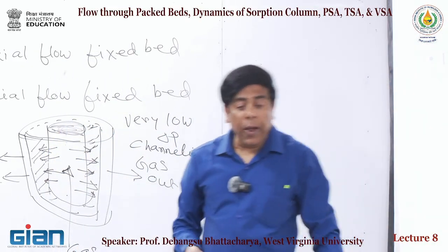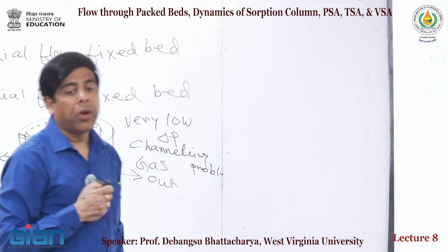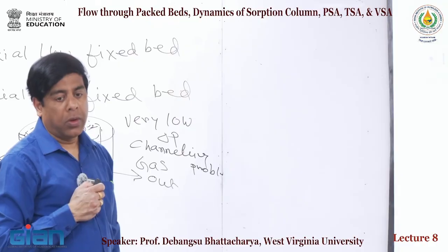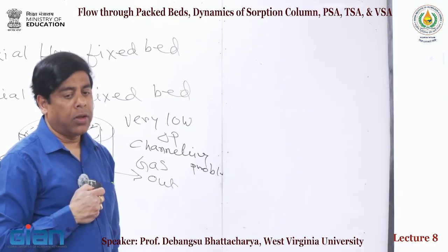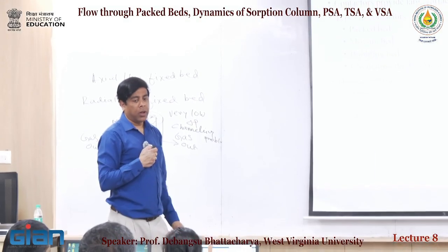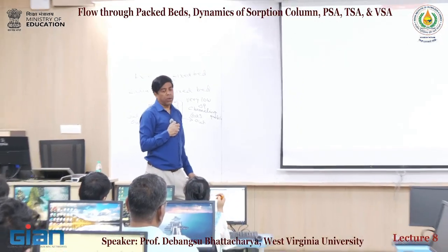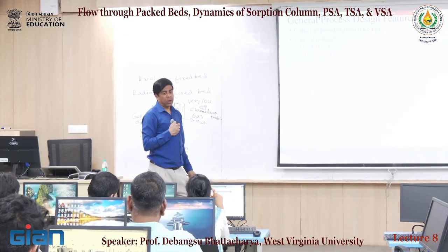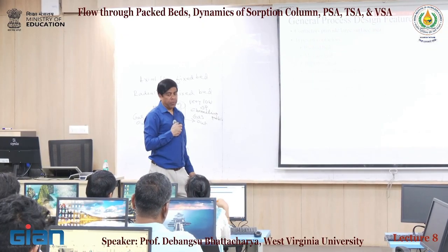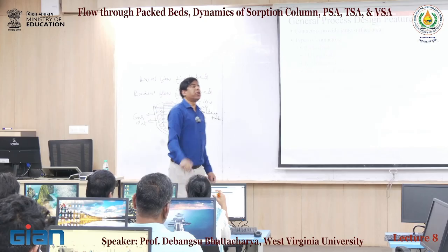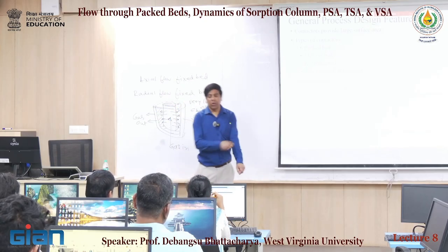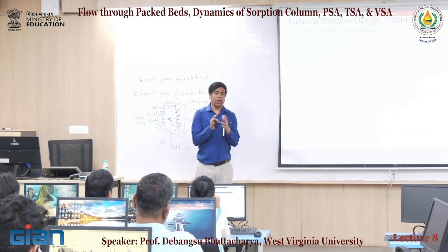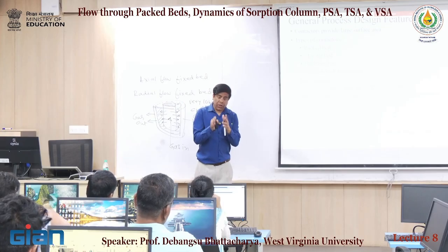You had a question? We have cryogenic air separation units wherein we are separating CO2 and moisture using these dryers. There we have two dryers. One will be in line, the other will be in regeneration. Absolutely. So my doubt is we have packed beds only. We'll be sending the air, so inside the bed, will that be in a fluidized state then? No. The cryogenic systems which you are considering, those are all packed bed and fixed packed bed.